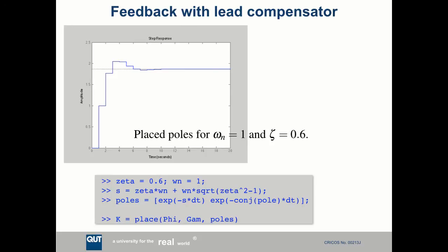And I do that simply by designing a pole placement controller for it, and I place the poles to give me that characteristic equation. So there's nothing extraordinary or unusual about taking something that's got pure delay, a very odd dynamic. In continuous time, in the S-plane, you can't represent something with pure delay. That's something that's really special to the Z-plane, where pure delay is represented by a pole at the origin. But we can make it behave like a lovely second order system if that's what we want to do.